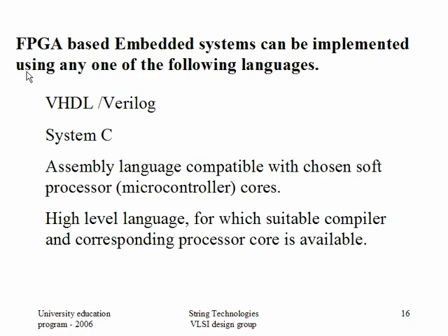What I'm trying to say is, when you are implementing the actual logic, tomorrow either you are going for ASIC or FPGA, if it is the actual logic which has to run on the chip, we prefer VHDL or Verilog, because there the efficiency when you do synthesis is better: getting more speed and less chip silicon area is possible.